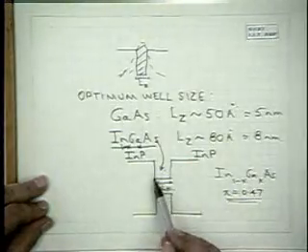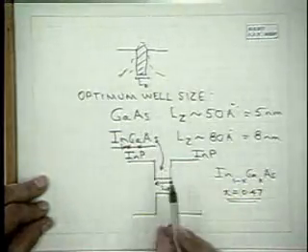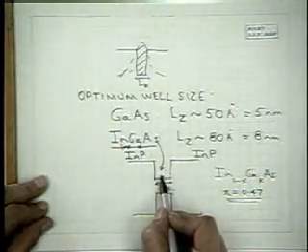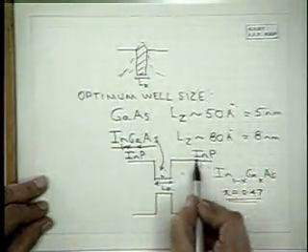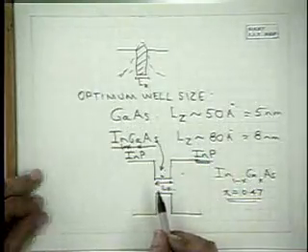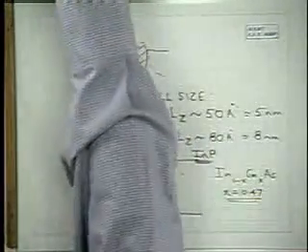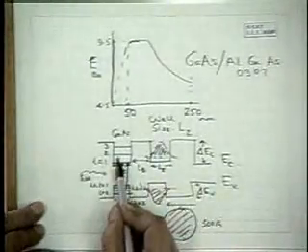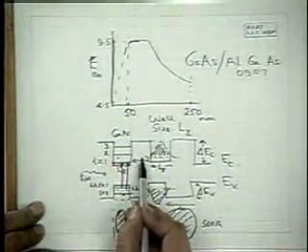The other difference between this system and the GaAs-AlGaAs system is here the well is an alloy, a ternary alloy. The barrier is a binary compound. In the case of the GaAs-AlGaAs system, which I showed here, the well is the binary and the barrier is a ternary alloy.